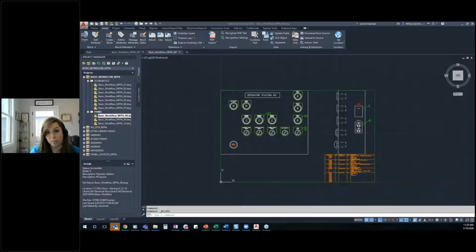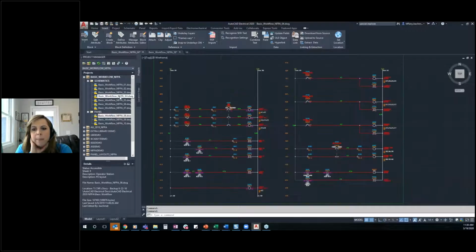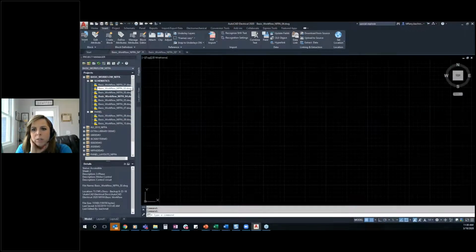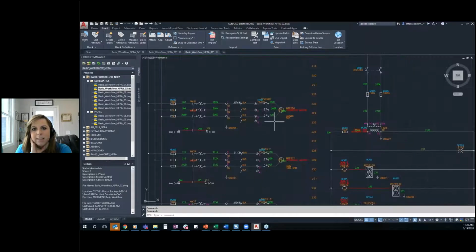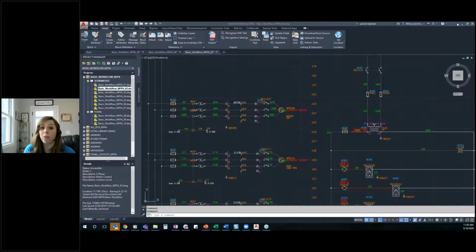Yes. So Fusion and Eagle are very much meant to be around electronic design. So it's a lot more about the PCBs, all the circuit boards, that kind of thing. We do circuits within electrical, but they're not in the sense of circuit board creation like that. That's really not the use case for electrical. So when you look at circuits, you might look at a motor circuit like this, but it's not going to be in the PCB style of setup. You could twist electrical to do that, but that's really not its use case. However, we have lots of symbols for electronics, and you can absolutely use it for that if that was needed.